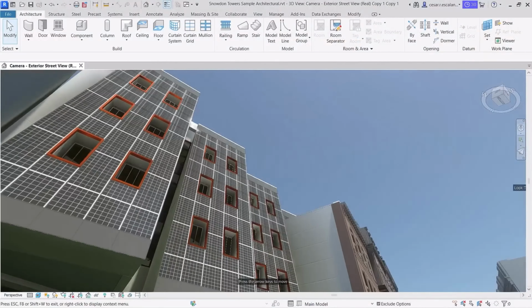Grade surface points more efficiently with the point editor, just as you would use the familiar shape editor. Display patterns aligned on an entire surface of shape-edited floors. Enhancements for visualization help architects tell a more complete and compelling story for their design concepts and explorations. AutoSync with Twinmotion for Revit provides a live link between Revit and Twinmotion. Other visualization upgrades include a new visual style that displays material textures consistently, while minor enhancements to sun and solar studies reveal the solar path with down to the second precision.